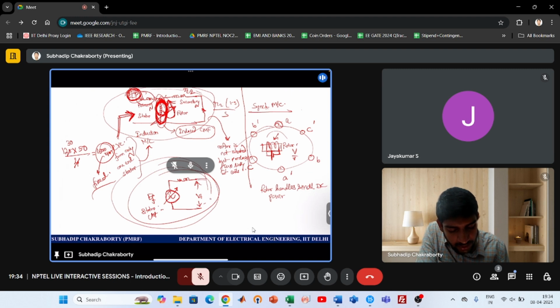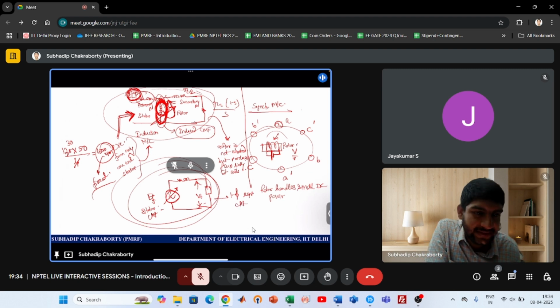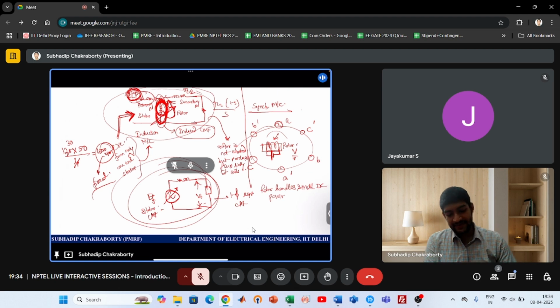So if you have some load, this is a single phase equivalent circuit, right? So this is a 3-phase system, but we are drawing the single phase equivalent circuit. Phase A, phase B, phase C all will be same, like this only. So what I told you, that if I have control over this and I am giving something from this side, like in a motor I am giving VT, I am also controlling the EF because I have the excitation in my hand. And similarly, I have EF as a generator. I generate some voltages and I power the load.